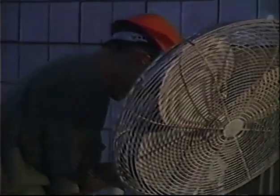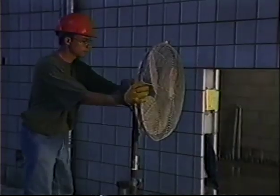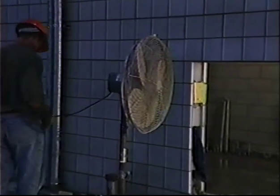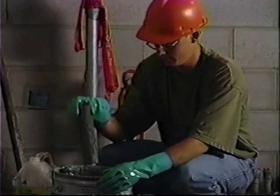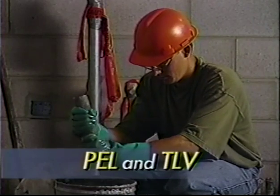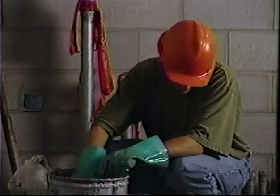Start with engineering controls. Increase ventilation by using fans and opening windows. These help lower the concentration of vapors and reduce your exposure to the solvent. Know your exposure limits. Remember, the PEL and TLV tell you the maximum concentration of the solvent in the air that you can safely be exposed to. If you feel sick at any time, tell your supervisor.